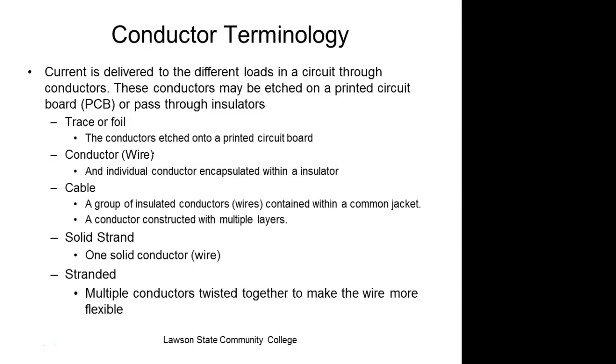And people don't know that. They'll take that stranded wire, wrap it around the screw, tighten it down, and half the wires come out from under the screw. So what we have to do on stranded wires is put terminals on them. We have these crimp terminals or these solder terminals we put on there. Or we put it in something where the strands can't get out. They have a horseshoe type thing. We'll put the stranded wire in there, and then we'll bring a thing down on top of it. And we don't allow the wires to spread out. We call it bird caging.